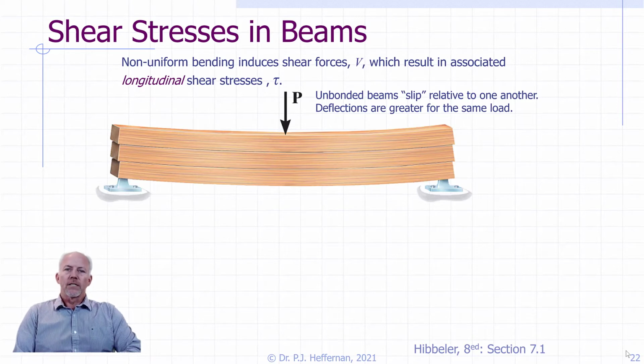If the friction was strong enough to overcome those longitudinal stresses, then this pile of 3 2x6s would start to behave compositely and act like a single beam, rather than 3 little beams stacked on top of each other. The way to overcome that is to find a way to connect these 2x6s so that they're all behaving dependently, and we do that by bonding them.